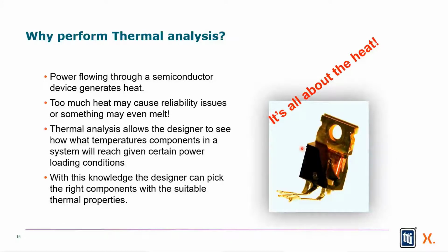Remember, MOSFETs are all about the heat. If you can remove the heat, you can put more current through it. So it's always about getting rid of that heat, not generating it in the first place. And then if I do generate it, getting it from inside the package to outside to my heat sink or fan or water cooler, whatever it is, as quickly as possible.